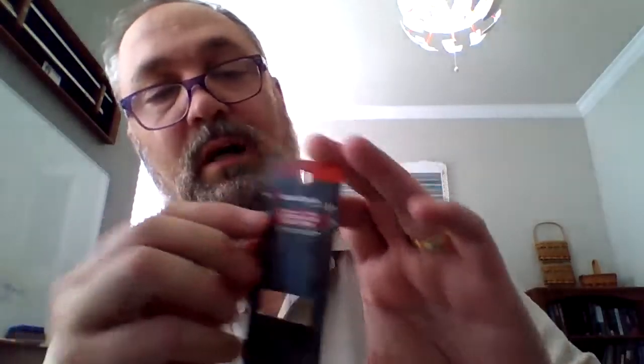You can find them in hobby stores. And what you'll notice is up here at the very top, it says 1/4 watt resistor. When they're about twice this size, they're 1/2 watt resistors. And when they're 4 times this size, they're full watt resistors. And those are usually the sizes. They do make 1/8 watt resistors, which are itty bitty ones. I don't like using those because they're real likely to burn out.